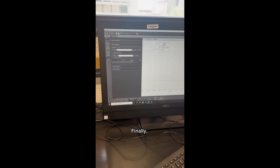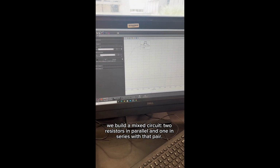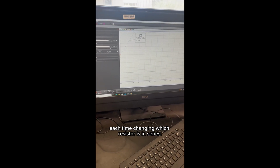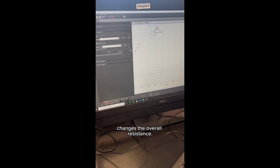our conclusions. Finally, we build a mixed circuit, 2 resistors in parallel and 1 in series with that pair. We'll repeat the measurement 3 times, each time changing which resistor is in series. For each configuration, we record the slope and compare how adding a series resistor changes the overall resistance.